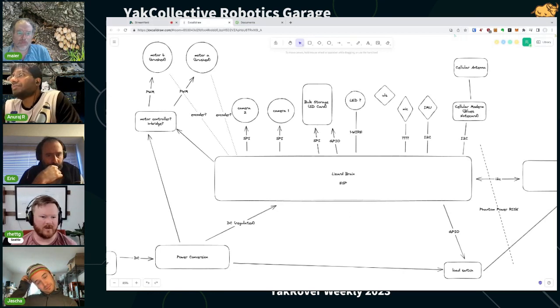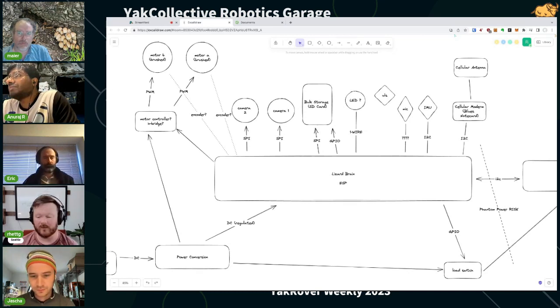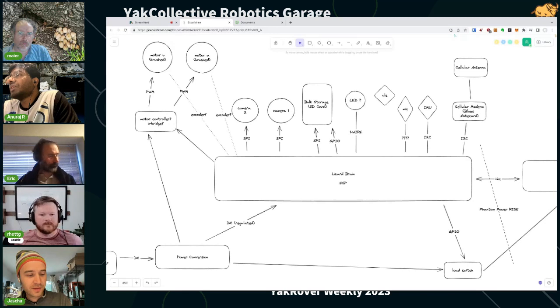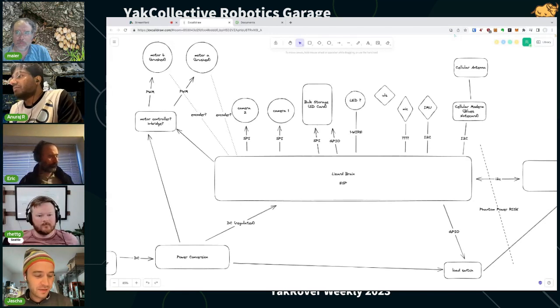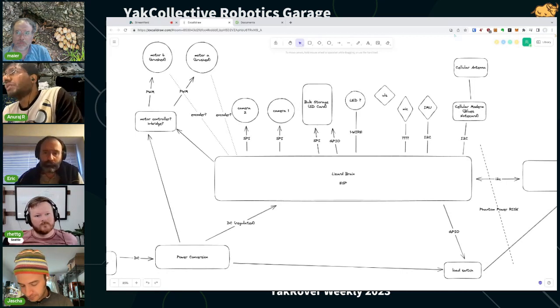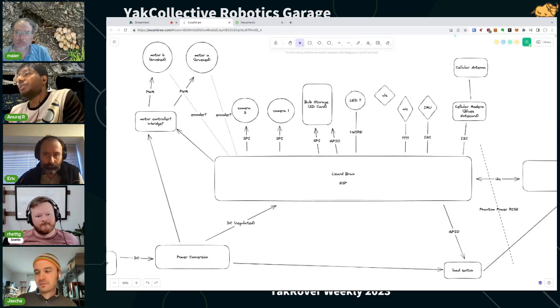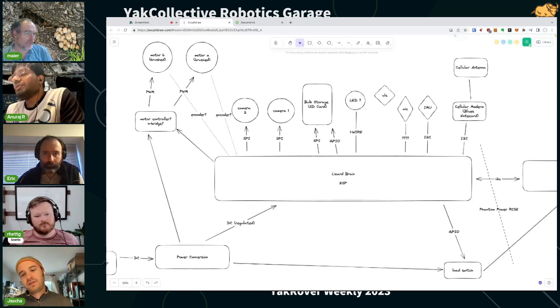I think it would definitely be helpful in development to be able to use Wi-Fi as opposed to paying per byte for cell phone. But Arnold, are you saying it would be good to get rid of that constraint to open up the component selection to STM or Atmel or whoever? Yes, what would be the use case? Because that radio will consume some more power, right? If we just have the micro without the Wi-Fi radio, you don't have to turn the radio on. Yeah, it's just there. You don't have to use it.